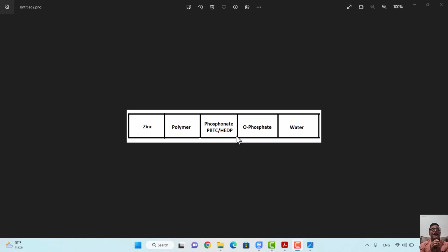As I stated, we have different types of phosphonates. We have HEDP, AMP, PBTC, and of course, HPA. And as I stated, some of these types of phosphonates are impacted by the level of chlorine in the water. They are not resistant to a high level of chlorine in cooling water.